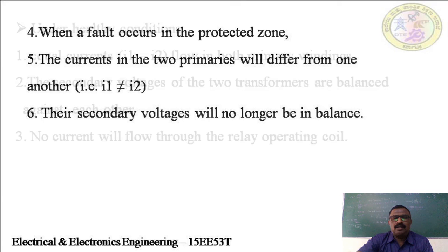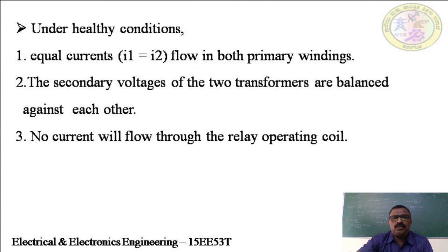Since the induced EMFs cancel, there will be no current flow through the relay operating coil. Whenever there is no current passing through the relay operating coil, the relay is said to be inoperative.